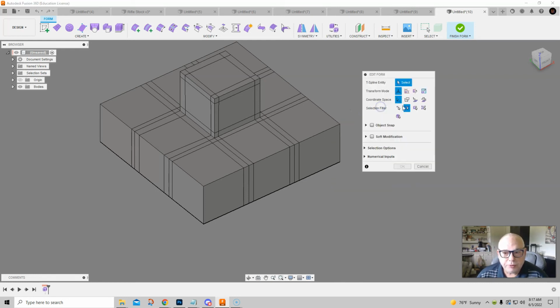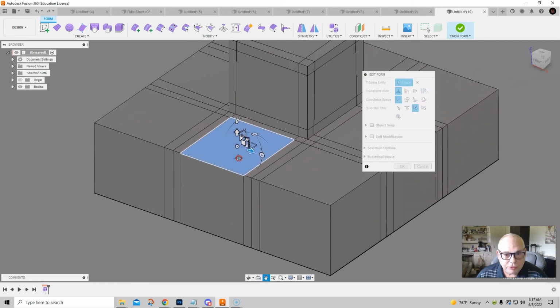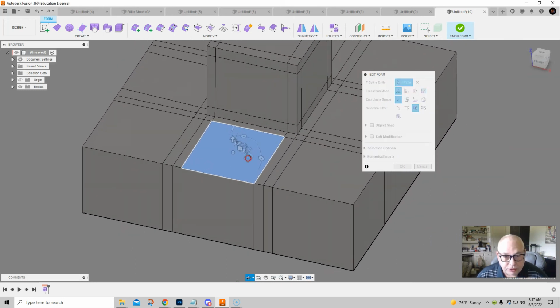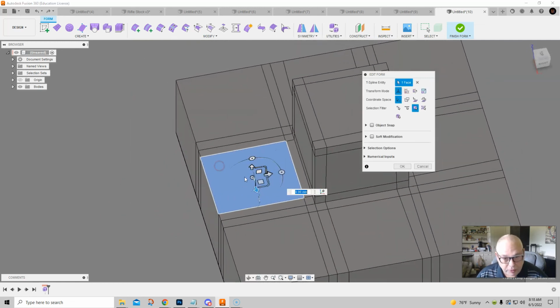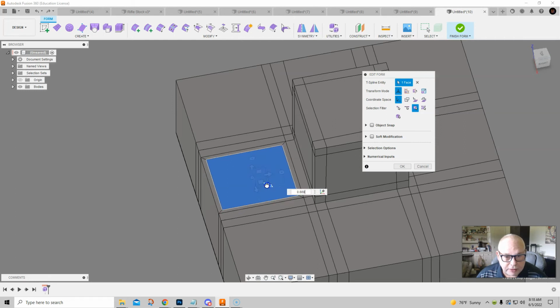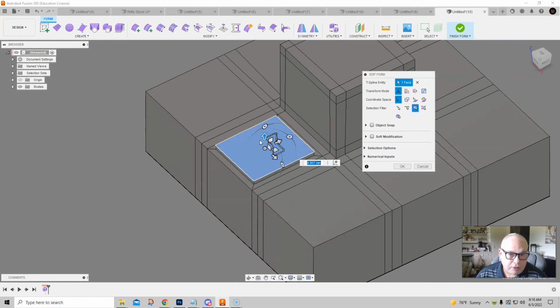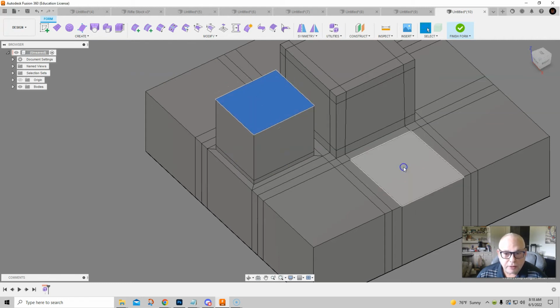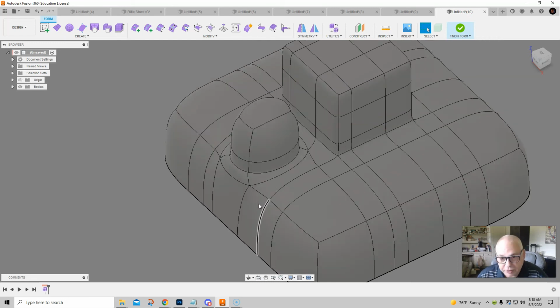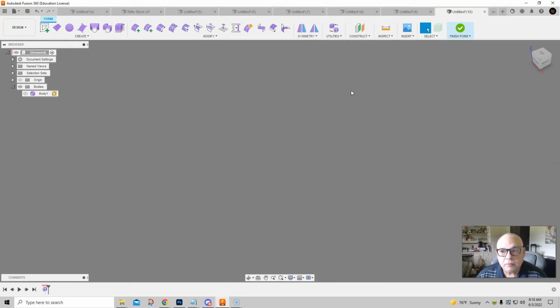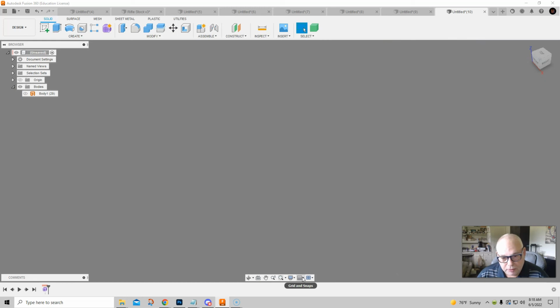Okay, so a typical thing would be to take this and extrude that out, but I wanted to hold that hard edge in here, so I'm kind of building subdivision surfaces. So I'm going to hold down my Alt key and drag this corner. This is scale, and I can scale it in a little bit there. Then I'm holding my Alt key again, pull this up, and then pull it up again. And then we've put locking loops in there as we're modeling. So let's finish that. Let's turn our grid back on.